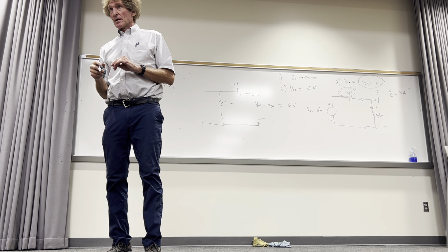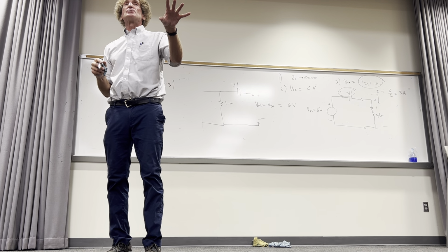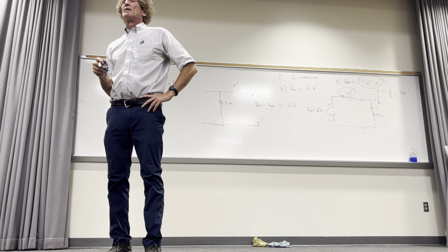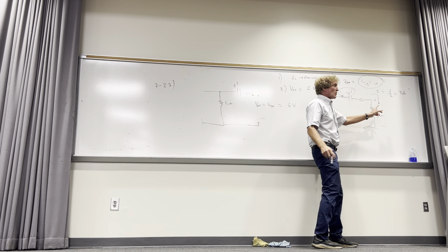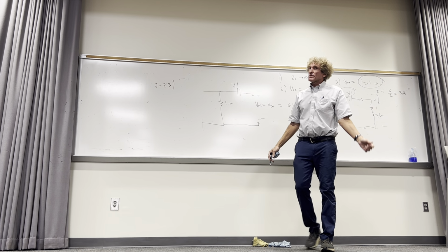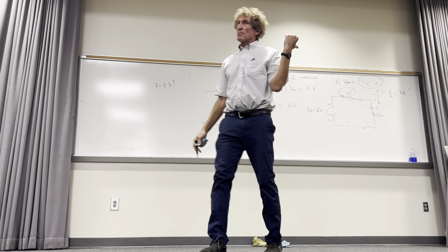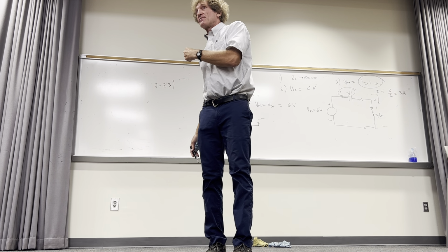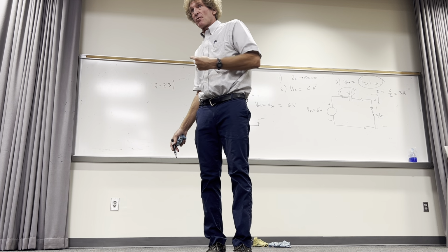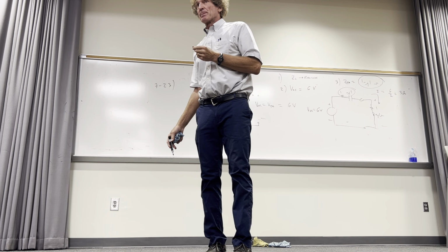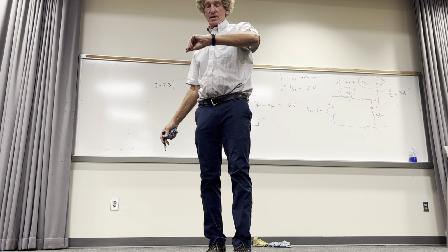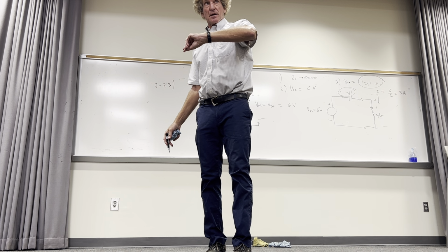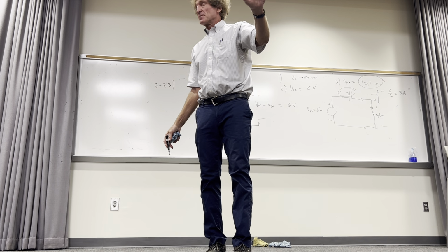Yes, sir. Sir, hold it. Speak up. Power supplied would be the power dissipated by the 1 ohm resistor here and the 1 ohm here, right? Well, there was 4.5 watts in the 1 ohm at the load. There's exactly 4.5 watts in the 1 ohm in the source. The sum is 9. With me, everybody? Okay. I mean, ask questions if you don't see something. There's no dumb questions.